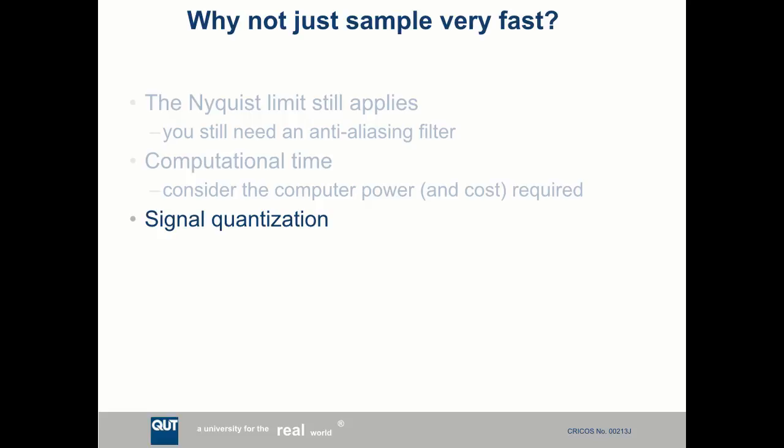And it should be in phase with that, yeah? So it becomes like a staircase instead of a continuous signal. So that's quantization. It's quantization in amplitude, in value, not quantization in time, which is what I've been banging on about most of the semester. This is quantization in a different dimension. But they interact in a really bad way, which is what I'm going to show you in a moment. So signal quantization is important.